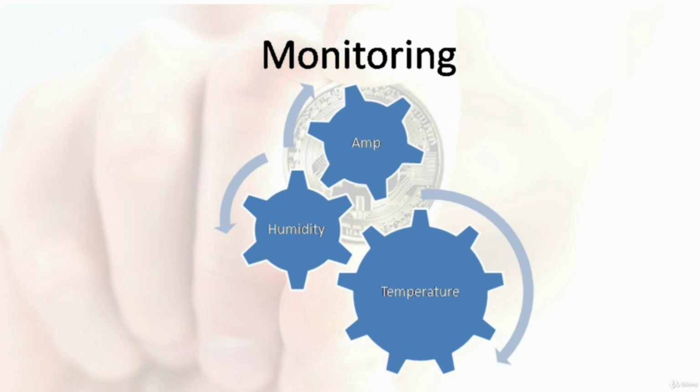You should also install ambient temperature sensors to monitor the temperature of the entire room. These sensors should be plugged into your network such that they can send the information to you remotely to give you real-time updates of temperature changes. The same ambient temperature sensors should also be equipped with humidity measuring capability. At least, I would suggest you get sensors that measure both.